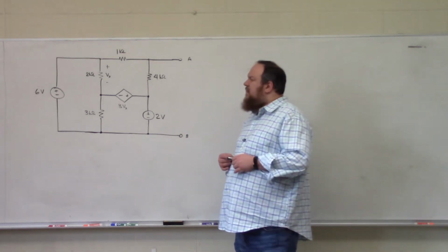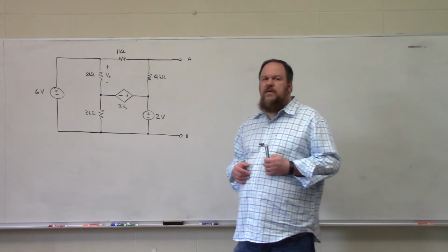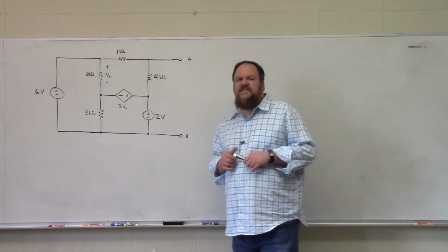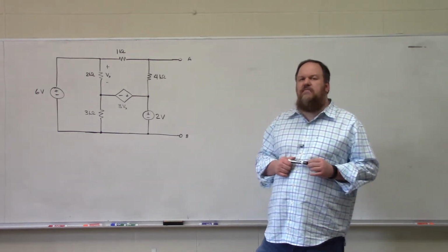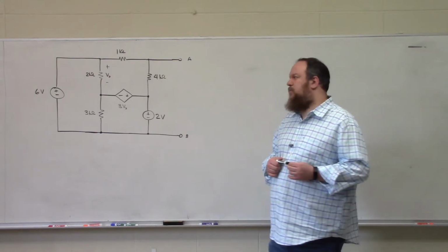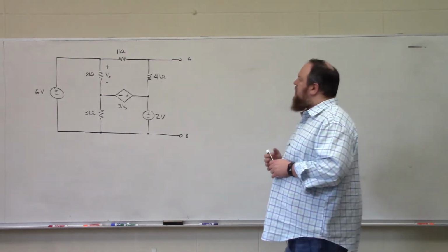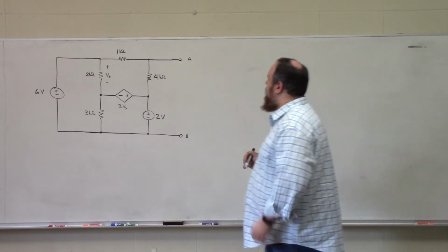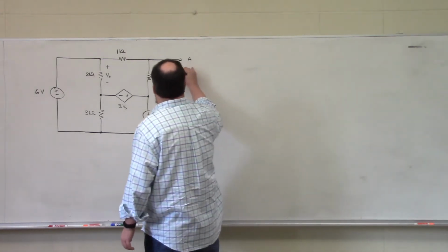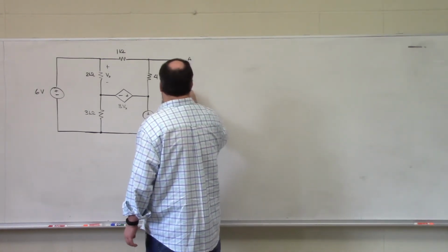So instead, we're going to have to rely on the relationship that the Thevenin resistance is simply the ratio of the Thevenin voltage divided by the Norton current. So for this circuit, let's first find the Thevenin voltage, which will be the potential difference between terminals A and B.